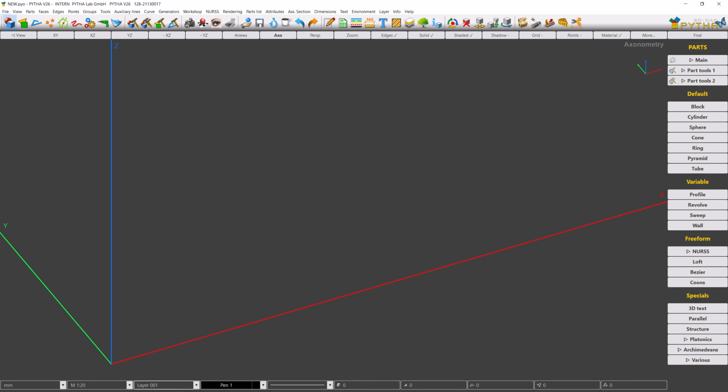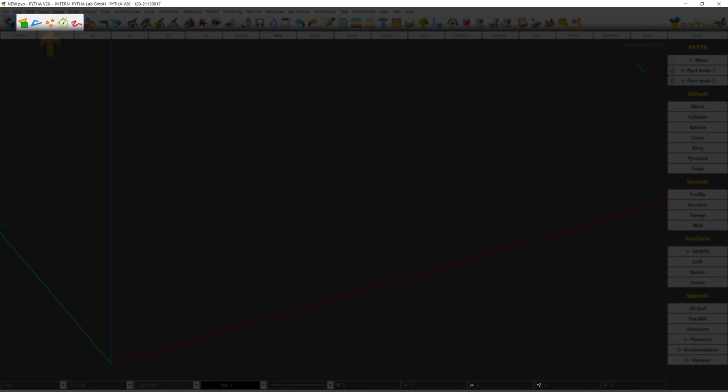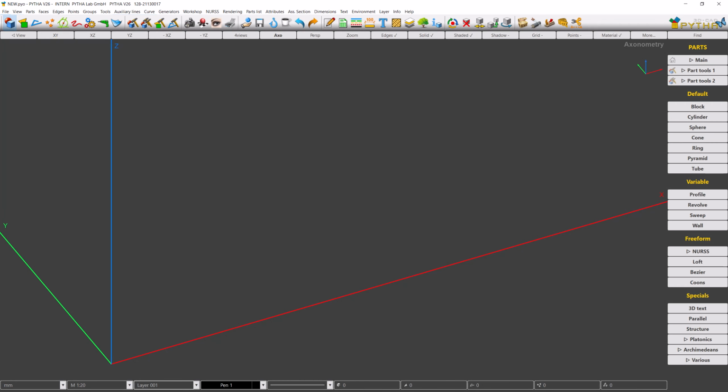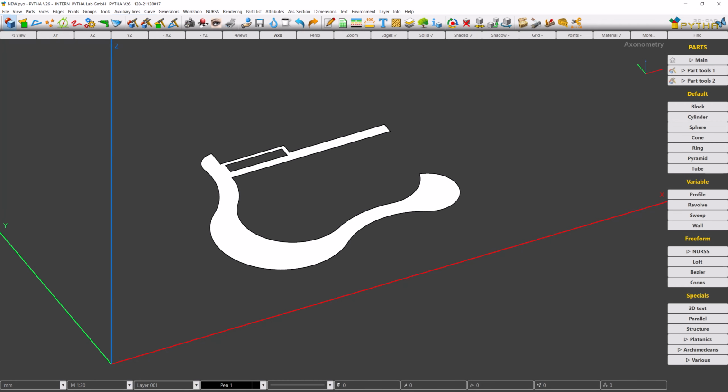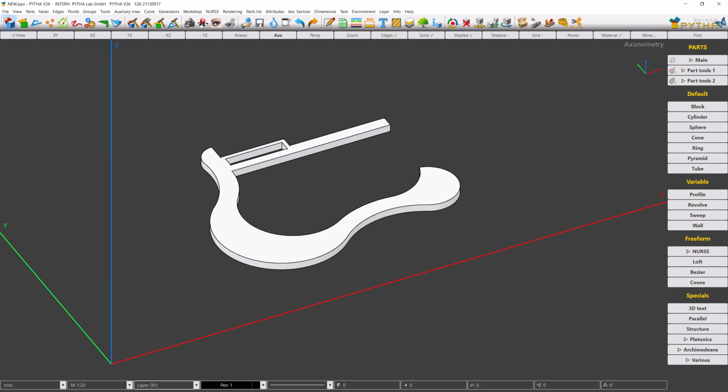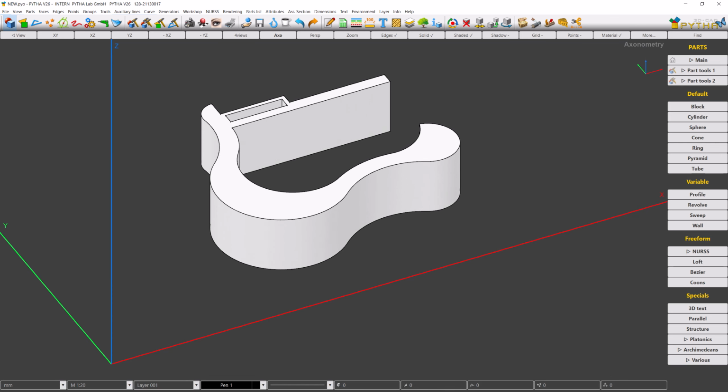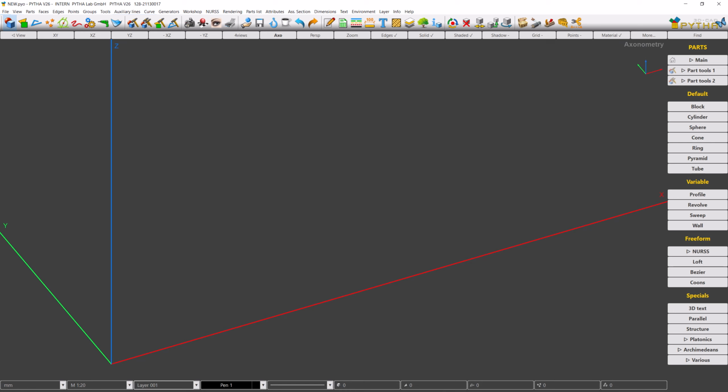This makes it easy to create worktops with curves, floor panels, curved walls, profile strips, logos, and so on. For a profile, you always first need a 2D cross-section. This can be defined by points, edges, faces, curves, and auxiliary lines. The Profile command sweeps the existing cross-section perpendicularly and creates skin faces. This creates a 3D solid of any length from the cross-section. So much for the theory, but now let's make a profile together.